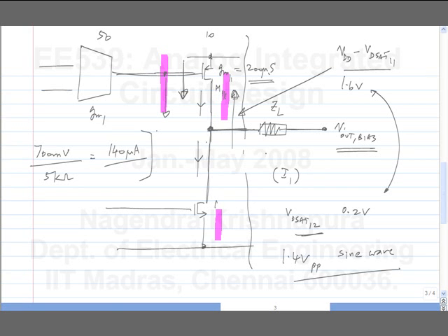So let's see how to do that. Let's say you chose the output stage. You can design backwards, starting from the output stage. This of course assumes that the gain of the second stage is fixed, which is also subject to change. You can design anything you want, but let's go with the assumption that I want the second stage of gain 10. After that you can change it if you want.